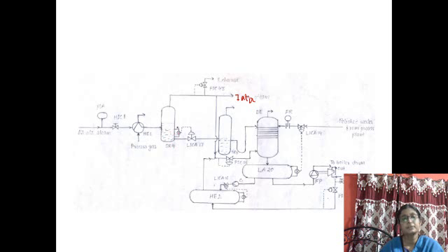that means the drum, there exists a level control loop LICA 17. Again, this 17 does not have any significance, it is nothing but a tag number. This is a level indicator controller along with alarm facility. The level should be checked. See, this is the typical symbol in a PI diagram for a level controller. Level always should be measured for upper as well as lower level. So level should be symbolized like this, and this is the measuring device.